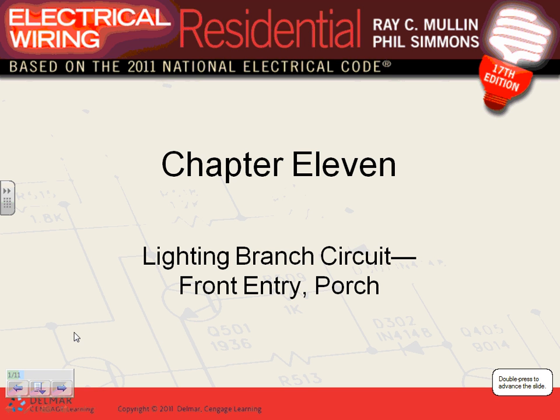Okay, very simple chapter, guys. Chapter 11 talks about the lighting branch circuit for the front entry porch. I want to warn you, Phil, my friend, in the residential, they use the word lighting to mean also receptacle. So as you can see here, they mean also sometimes the word lighting and general purpose receptacles. So don't be surprised when they say we talk about lighting and there's a receptacle stuck into that lighting circuit.